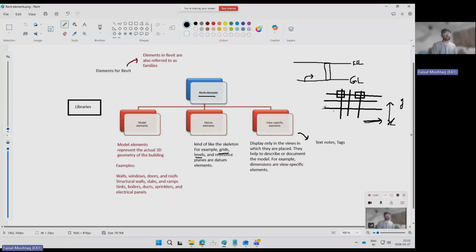So you see that those grid lines are crossing each other at certain points. For example, those common intersection points are there, and we place structural elements, for example, columns, beams, by referencing those points, right? If I want to create a column, I need to snap that point. It automatically snaps that point. I pick a column, I snap a point, and I place it.